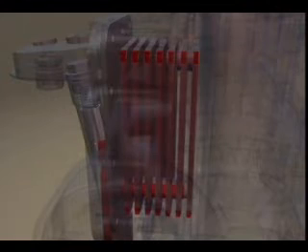The oil cooler element was redesigned for increased cooling capacity. The element cools the oil as it is moved through the plates and coolant is passed on the outside of the plates. The oil then continues through another cast passage in the oil cooler cover to the oil filter.